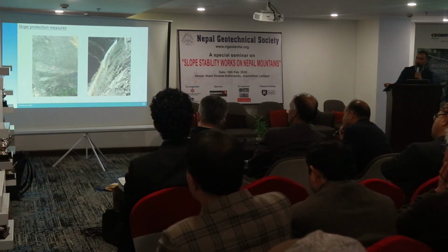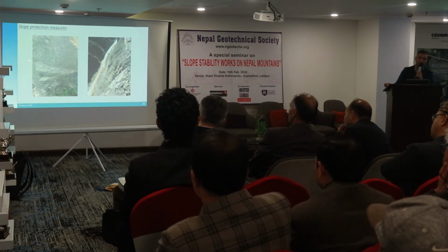And next is again the toe at the corner of the Upper Arun project, where the Arun River bends. You can see this one, it's not the foliation, but one joint, and it provides the kinematic feasibility of the whole upper part of the failure. The bottom part started not with this, just with a tension failure. At the bottom the rock failed in tension, and when it came to this joint, it couldn't support the upper part, and it just moved at, I think, one point.